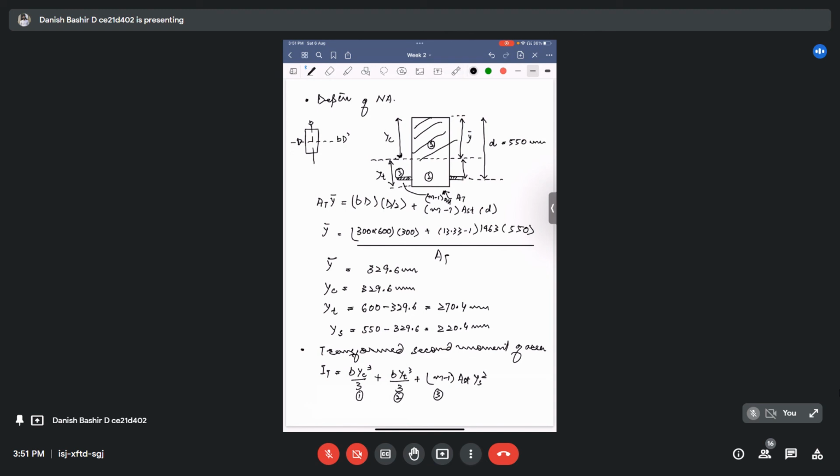So from the parallel axis theorem, the second moment of area about this axis is the original moment bd cubed by 12 plus the area of the whole section, bd, times the distance between the axes, d by 2, whole square. When we work this out, it comes to bd cubed by 3. This is just for if someone is not able to understand where bd cubed by 3 comes from.